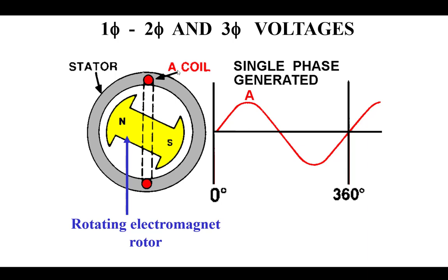We talked about induction occurring whenever conductors cut lines of flux, or there's relative motion. In other words, in this case the conductors are stationary, but the magnet's moving, so the lines of flux are moving and they're cutting the conductor. So there's still that relative cutting of flux, even though it's the magnet rotating in this case, where in the other generators we looked at, the magnets were stationary on the side in the field poles. Okay, so as this rotates around, we're going to get the sine wave, as we discussed when we were discussing sine wave generation before.